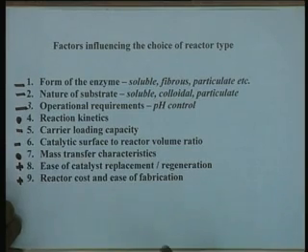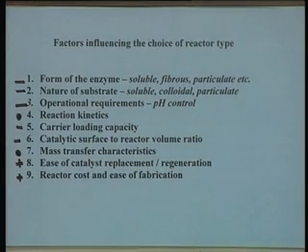Of course, I must again point out that the heat transfer requirement we have knowingly ignored, assuming that for most of the enzyme catalyzed reactions the heat of reaction is very small, and so heat transfer during the reaction is not a major critical factor. Of course, in certain cases, if it is so, the heat transfer characteristics also must be taken into account.